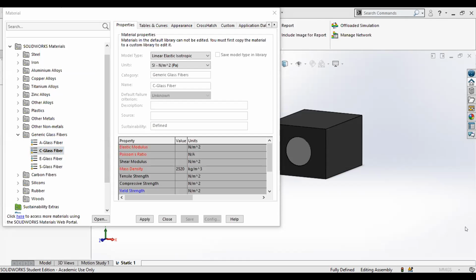What I mean is, I want to simulate, let's say, a fiber. I just put in an elastic modulus value that is close to my fiber's value. I don't need exactly the same as my actual fiber, just a value from the same group, because it's impossible for me to get the value for my fiber in the lab. So I just go to the internet, see this fiber has this elastic modulus, and put in the value for my simulation.